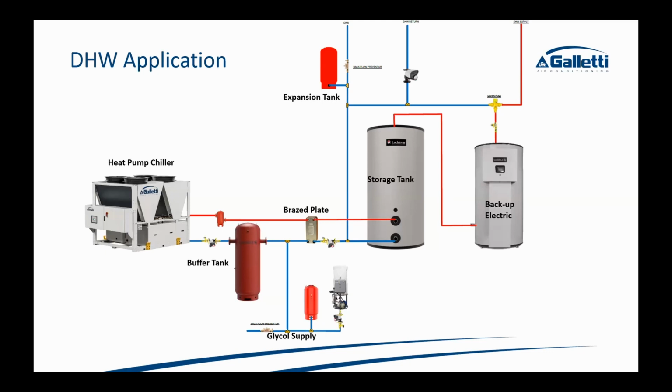And then on top of that, you're going to add another heat exchanger anyway to isolate the glycol circuit. So now you've got a heat exchanger at the glycol circuit and a heat exchanger at the unit, which could be double wall. Next thing you know, we have 4 walls to satisfy something that could have been a single wall, depending on the pressure, a single wall or double wall, and also depending on the state.